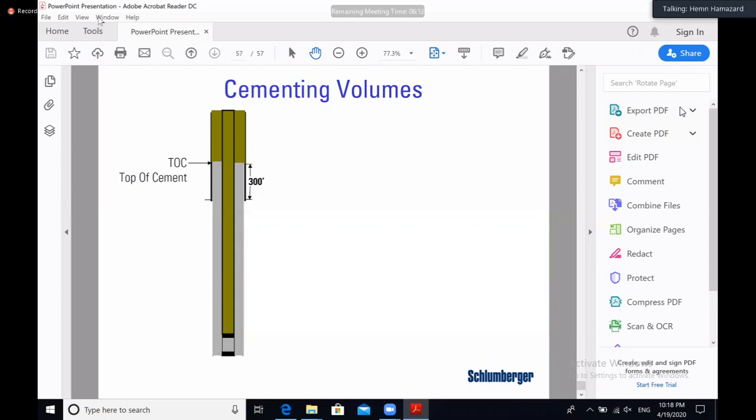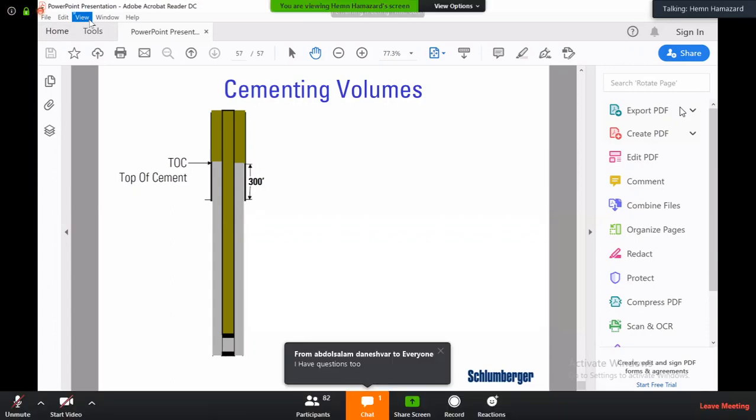Yes, we usually cement the conductor pipe also, just like the other casings. But for the cement head, we do it just with the mixer you see for construction. The people are using it. We just pour or dump some cement from the surface into the annulus behind the conductor pipe. That gives you your casing, your conductor will stay in its place and it doesn't move at all.